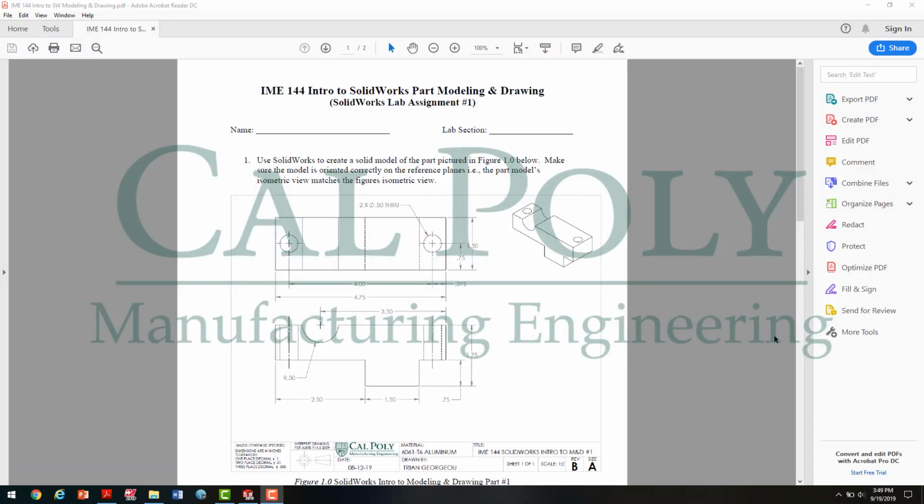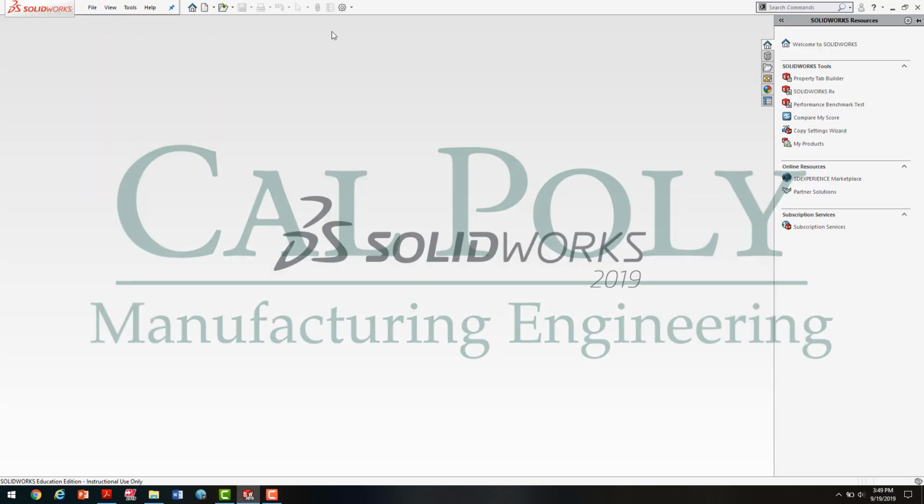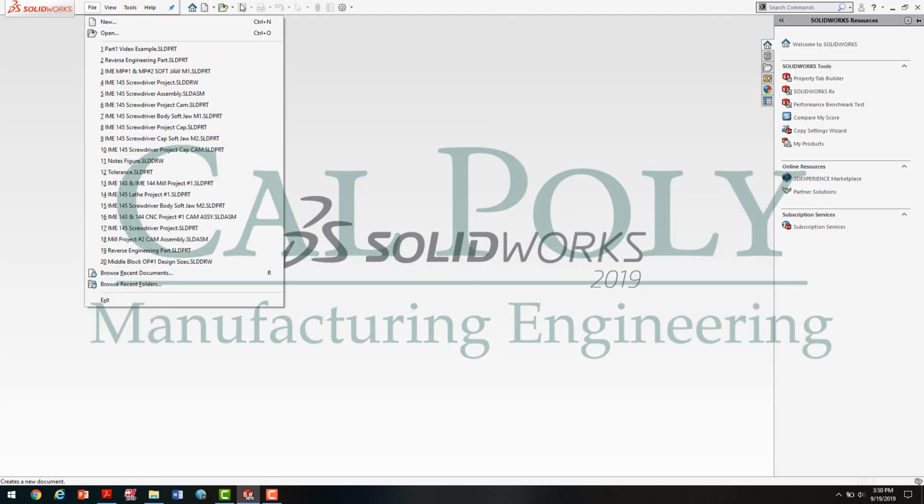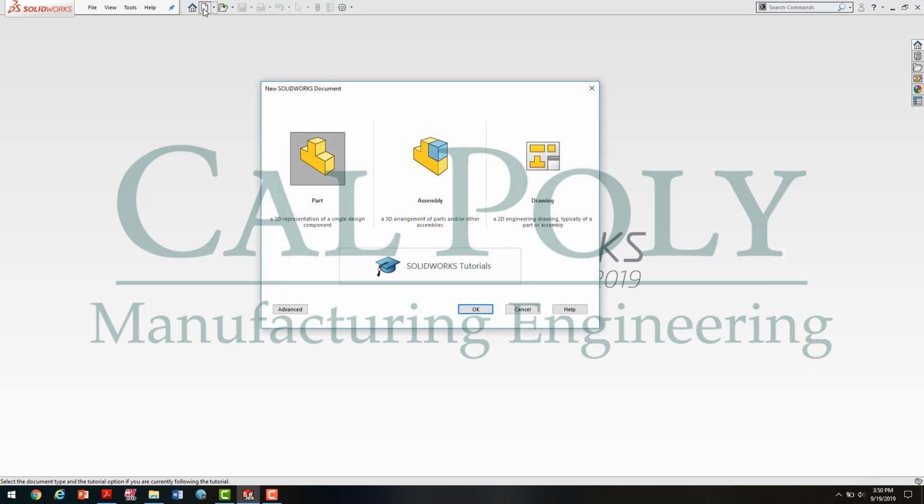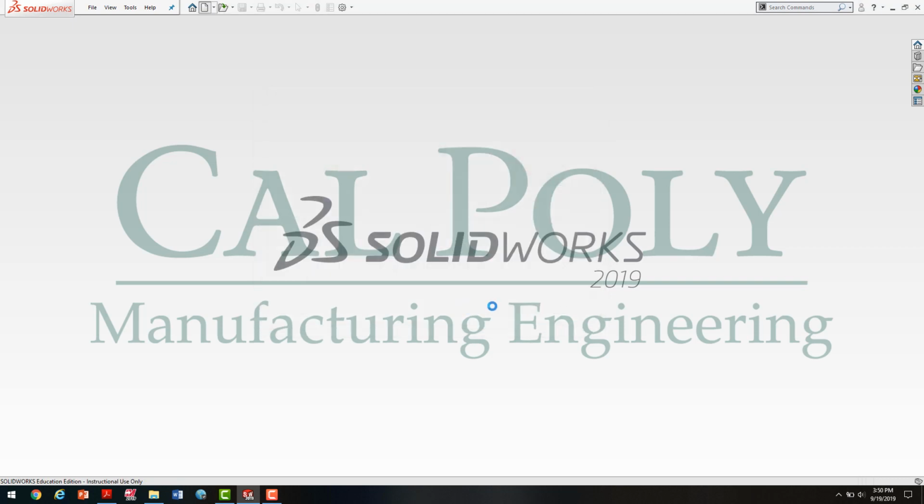In this video, I'm going to show you how to create the engineering drawing for part number 1 on our Intro to SolidWorks part modeling and drawing assignment. So our goal is to go ahead and create an engineering drawing like you see right here in the assignment. I'm going to move over to SolidWorks and I'm going to go File, New, same as hitting this icon up here. And this time I'm going to select a 2D engineering drawing by clicking on Drawing and pressing OK.